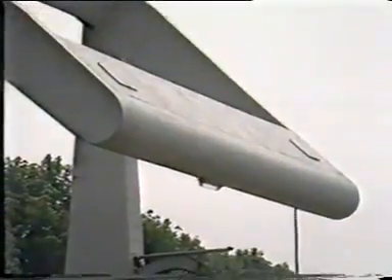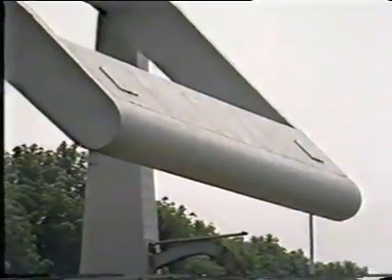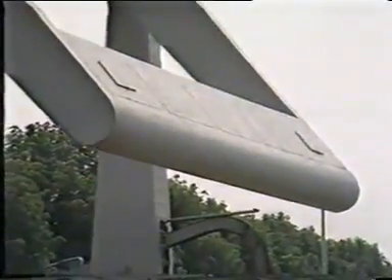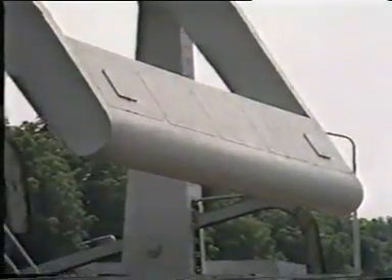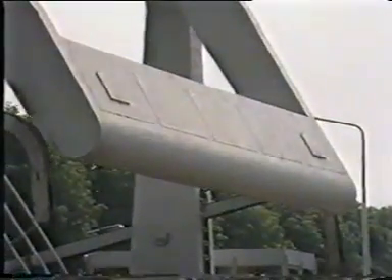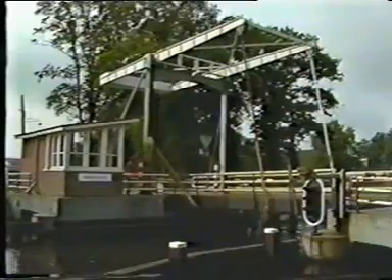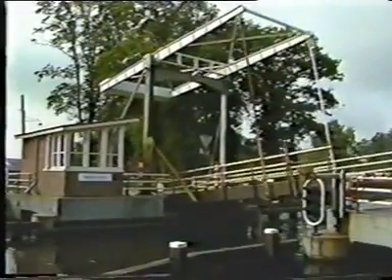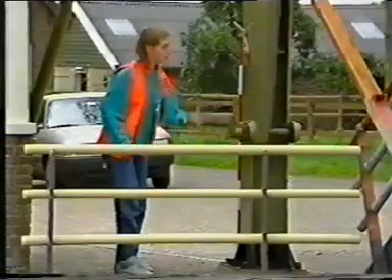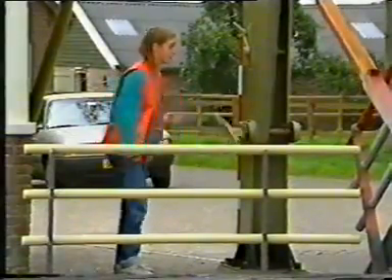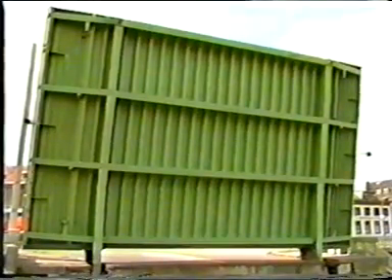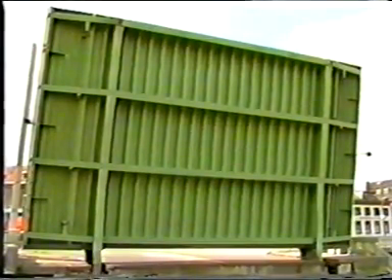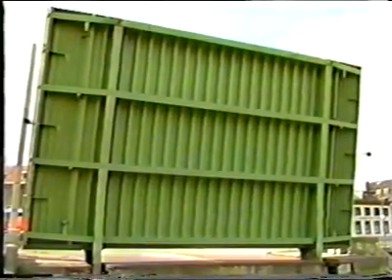In bridges with a timber deck, the counterweight is placed in a box girder. In this way, a rigid connection is created between the beams, ensuring that the bridge rises evenly. A one-sided drive becomes possible. The deck of a modern bascule bridge with overhead counterweight is usually designed as an orthotropic deck. It is composed of a deck plate, stiffeners and cross girders.